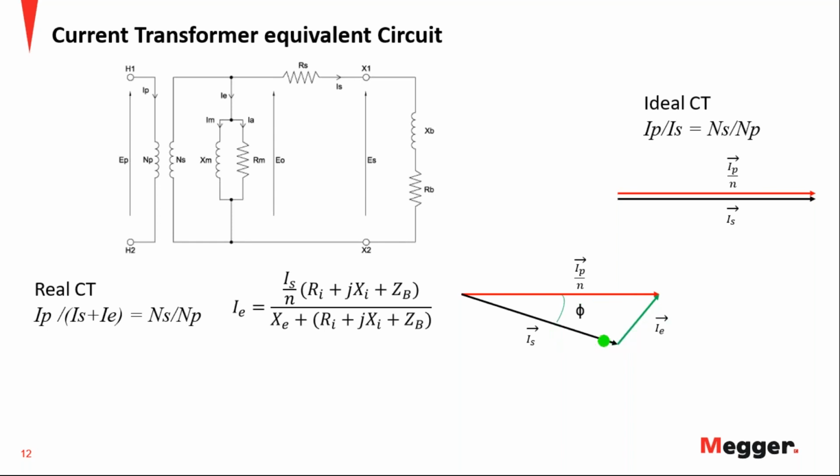So that's where you get your maximum and minimum ratio correction factor. And then for the phase deviation, we know that the limit is between 0.6 and 1 power factor, that is the corresponding cosine of this angle. So in this case it means that you may have a deviation that is lagging more or lagging less, because we are always on the lagging side, at least for this case. So that defines your 4 limits.